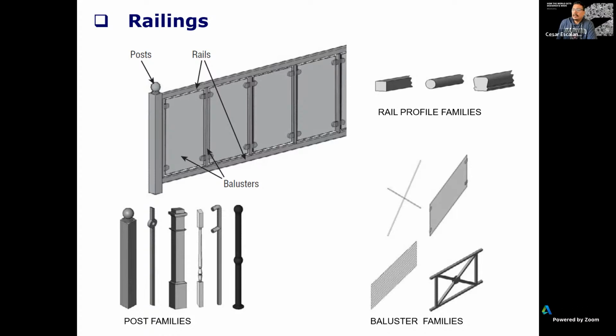And usually there is a built-in rail definition that is special, I would call it. Those are the rails that help for handrail supports, the ADA handrail supports, the ones that stick 3 inches away from the line of the railing. And you can build those definitions also in the type properties of a railing.